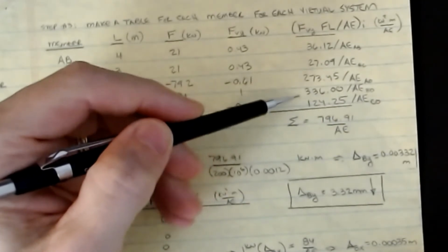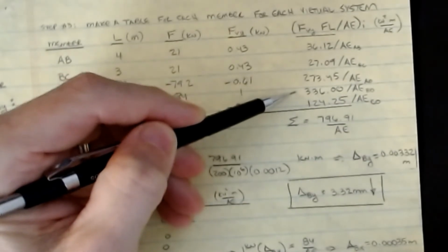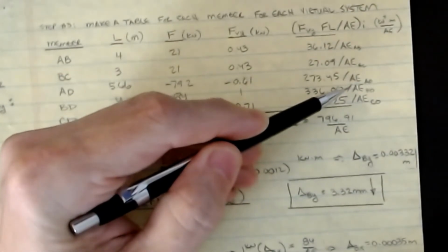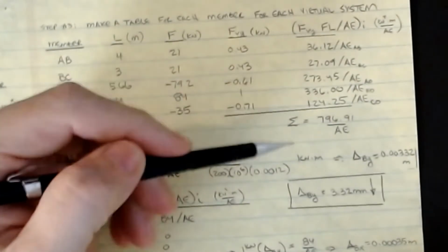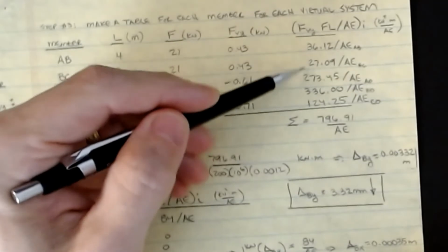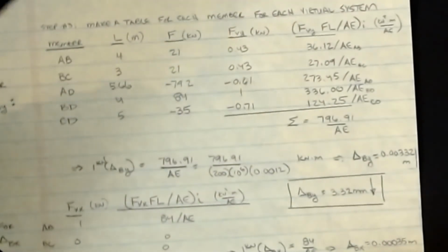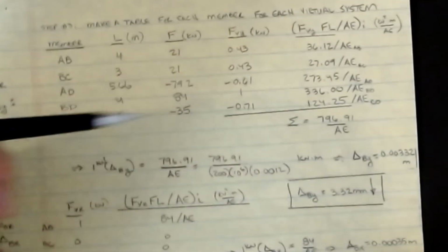So if I wanted to make the deflection smaller, all I have to do is decrease this work energy calculation, and I can do that by making A or E bigger or different on that, and all of a sudden I can greatly change the deflections. Whereas if I change these two, it would only change it a little bit. It's these two guys that are the biggest. So you can see some interesting things come out of the work energy calculation.